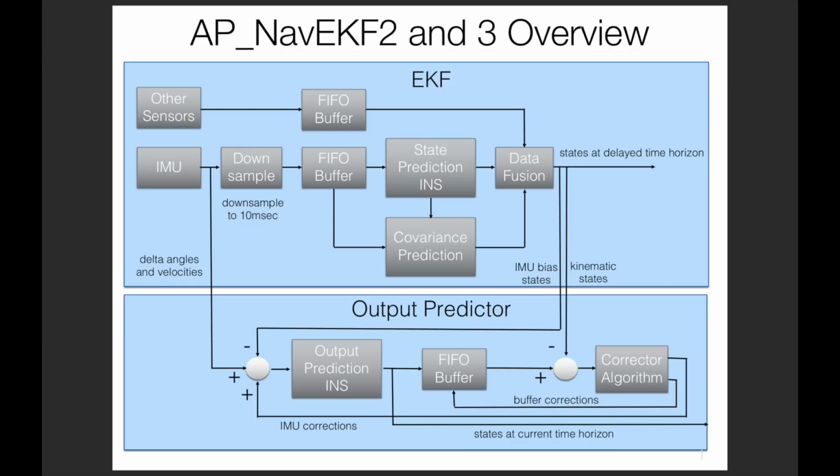So that's 3 states to add? No, it's not 3 states. Well, it's a minimum one state just for the scale factor. The visual odometry system will have these arbitrary length units, right? Now, I've moved 3 length units to the right, but they're not meters.